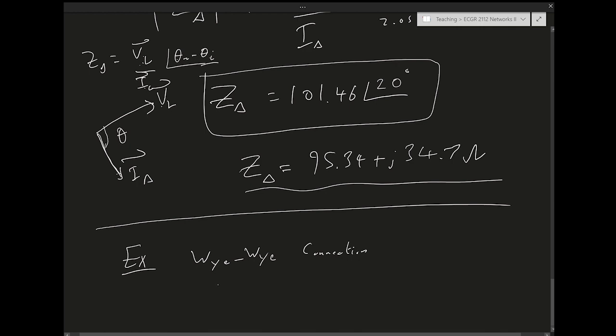Right, and then we have the phase voltage being 120 volt RMS, and then this Y to Y connection. Let me draw it this way. Before it goes into the load, there's some line impedance. This is actually a previous example that we solved last time. It's example 11.2 in the book, but we want to calculate the power for this example now. After the line impedance, there is a load impedance like this.